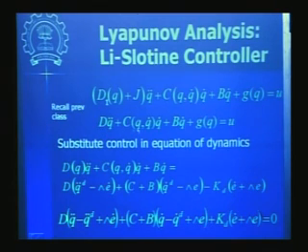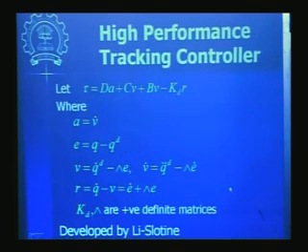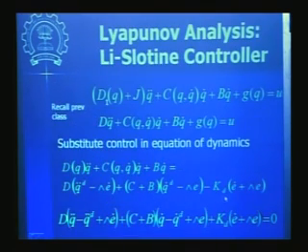So now we'll substitute in these equations the control law that we have just presented in the last slide. So this D times A, which was qd double dot minus lambda into e dot, plus C plus B into this term nu, minus KD into R term was there. This R we have seen to be e dot plus lambda e. Okay, so this gives us this equation.